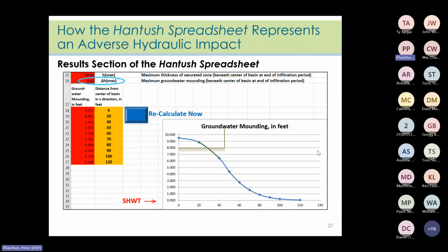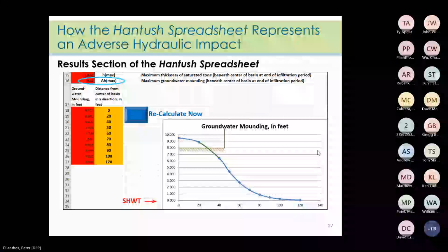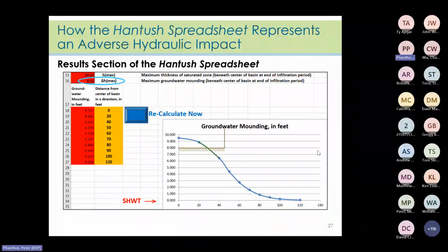For example, we would double the initial value for T if we halved R. Although we don't know the exact rate to which the rate would slow, even if it is slowed by 1/2, we're going to check the mounding for a value of T that is within the maximum allowable time period. Sometimes we call this stretching the infiltration period.